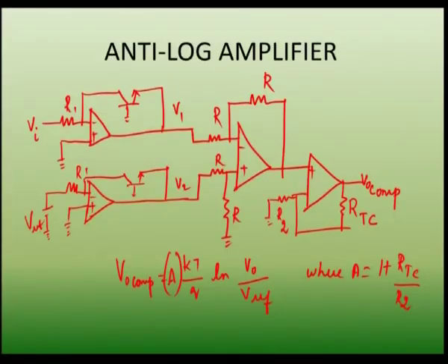So, whenever the temperature changes, this resistance value will also change accordingly, and so the effect of the temperature will be compensated by this circuit. And why we are giving a V reference in a separate circuit is that IS is the saturation current. The saturation current IS also decreases or increases based on the changes in the temperature.